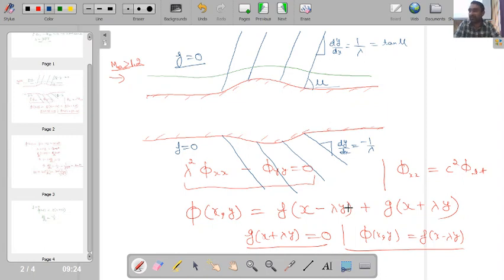Okay, over here in our mathematical analysis, by using linearized theory, we are not accounting for the shock wave, because the shock wave phenomenon is a non-linear one. So you can see over here that just by solving for the linearized velocity potential equation, we are able to somehow include the effect of the shock wave. Ultimately, you will also see later on in the value of Cp how this effect is coming.